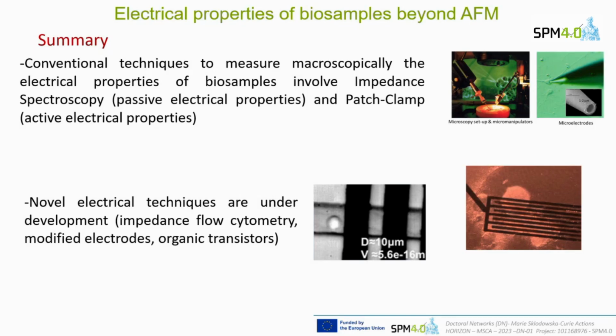This is something that goes in the direction of what is called laboratories on a chip. So the idea is that rather than using big instruments to do different experiments, you try to integrate everything into a chip and do the same experiments, but in a controlled environment, very cheap, very fast, etc. And one example I showed is this impedance flow cytometer, which can be used to count cells, to size the cells, and even to distinguish some different types of cells.